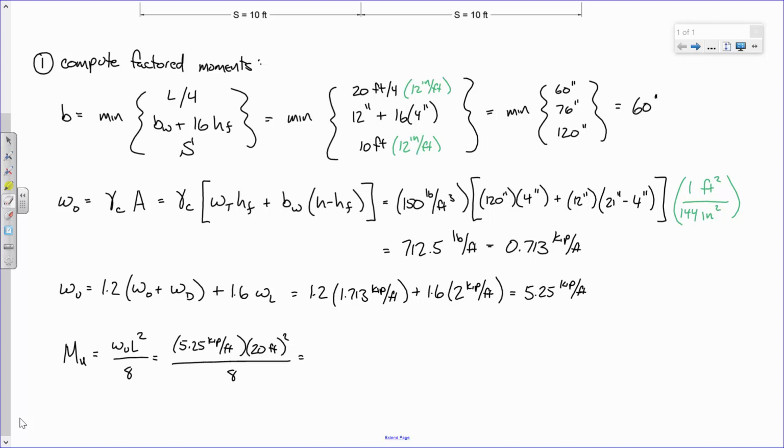Whoa. No. Ask that again. No, the shape of the beam does not affect the structural analysis. The only thing that the shape of the beam would affect is the moment of inertia. Remember when we calculate deflections, we need the moment of inertia, we need E, and we need I. And so I changes depending upon what the beam looks like. But it doesn't affect the moments really at all, unless it's indeterminate. In an indeterminate beam, the I changes what the response is. But we're not doing indeterminate right now, so we don't need to worry about that.